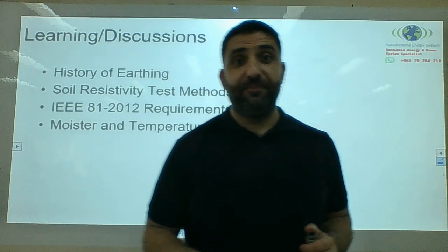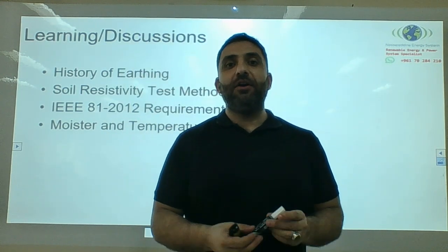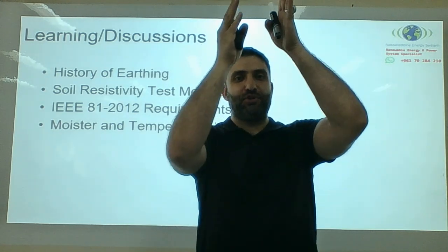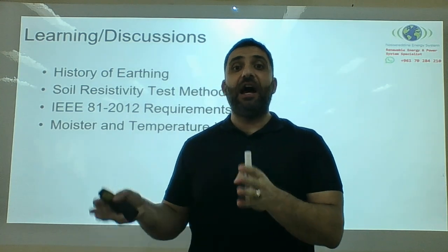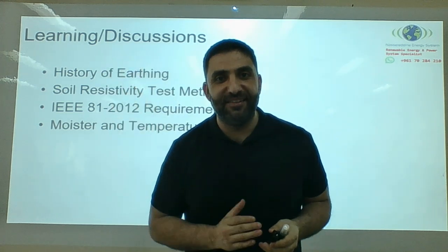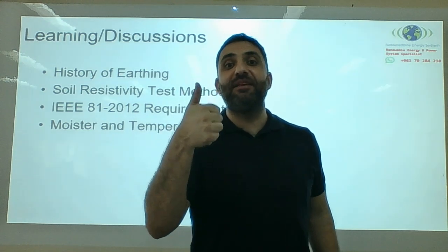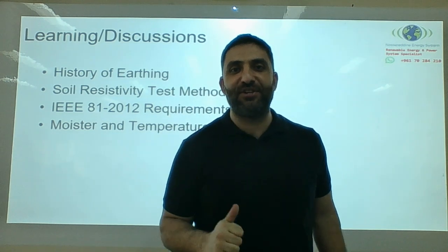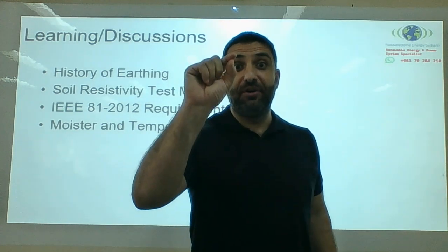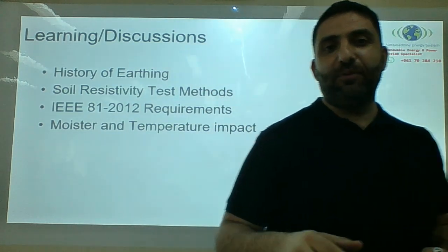I hope that's clear. Now, during our next session, or next lecture, we are going to take this measured soil resistivity from the table. Remember when we showed you the table, there's a lot of A, and how to use the IEEE 80 standard to establish a soil structure for us to use for allowable safety limit determination, and then for your earth grid determination, and then for your earth grid resistance calculation, and then for your step and touch voltage calculations under fault condition. I hope that's clear.